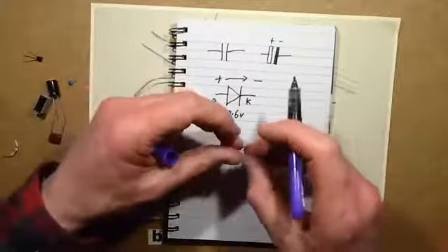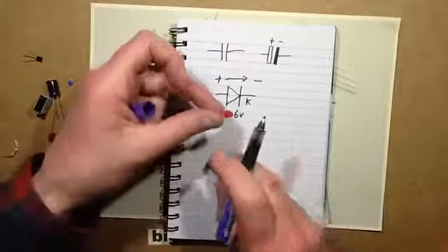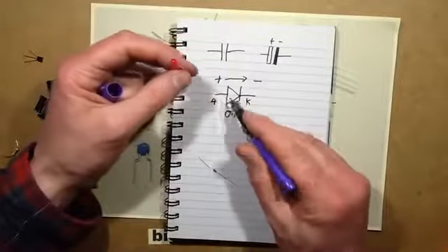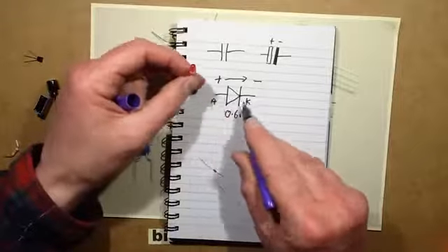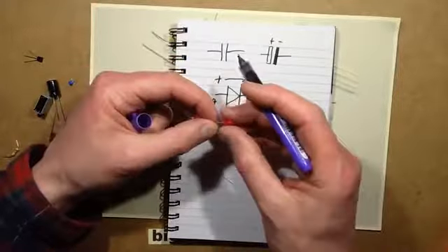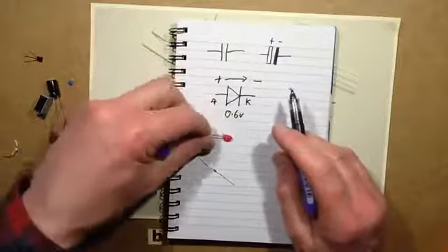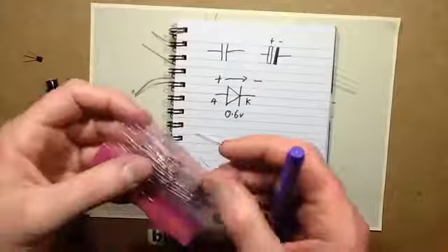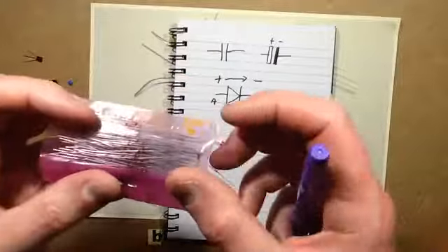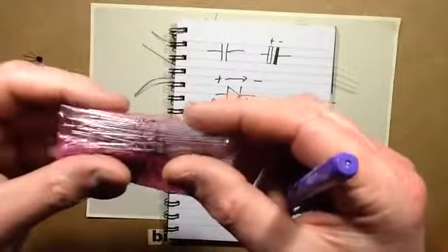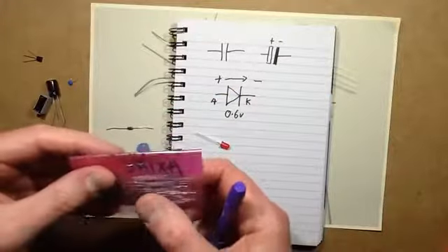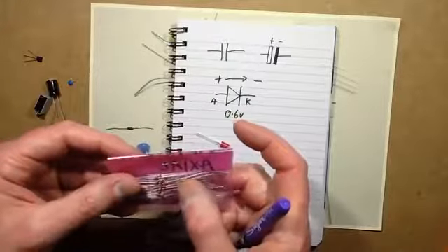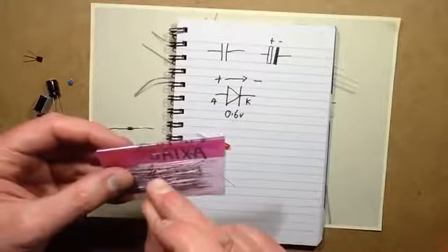The light-emitting diode, our favourite type of diode really, is a diode junction that is optimized. It behaves in a way like a normal diode, but when it's forward biased, when the current's flowing through it, it emits light. And the very first LEDs were actually, here's some here, they look just like the 1N4148. These are actually LEDs. They look just like ordinary glass diodes, but these are really vintage LEDs, and when you pass current through them in the correct direction, a little red dot glows inside them.